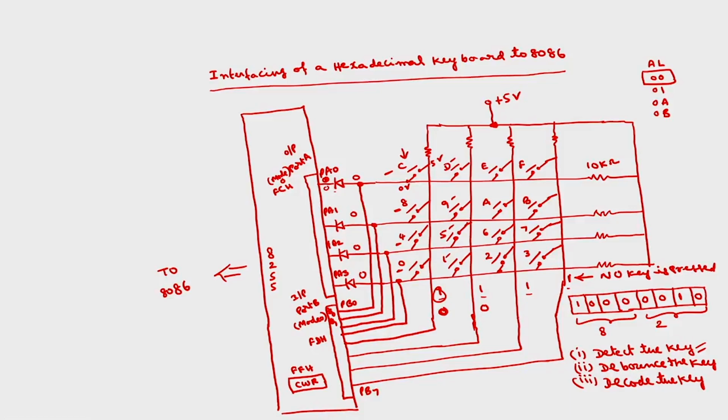So, before pressing any of these keys, what you have to do is, first check that all the keys have been released. Okay. After all the keys have been released, only then you press the key, otherwise you will get a problem of 2 key lockout. There is one problem with switches called 2 key lockout. It is whenever a particular key is already struck, if I press the second key, then two keys will be pressed simultaneously. That particular problem is called two key lockout.